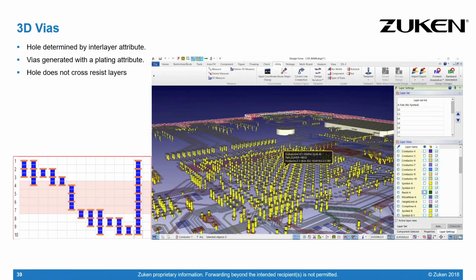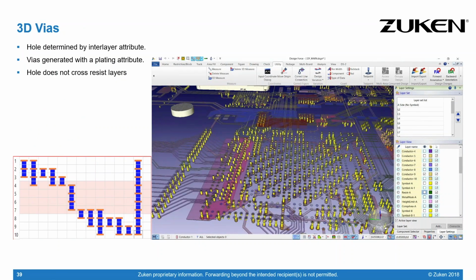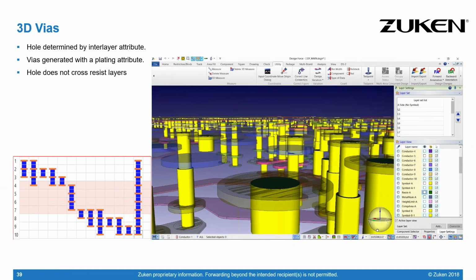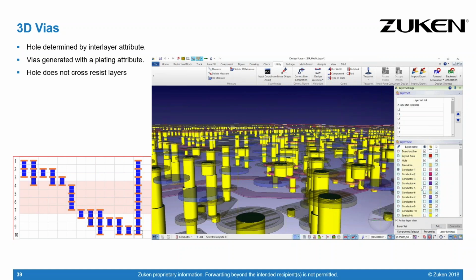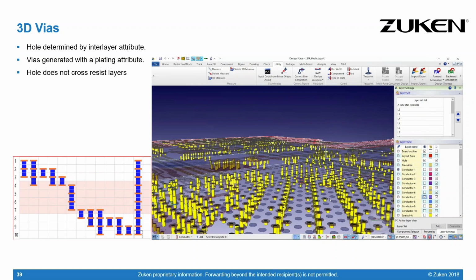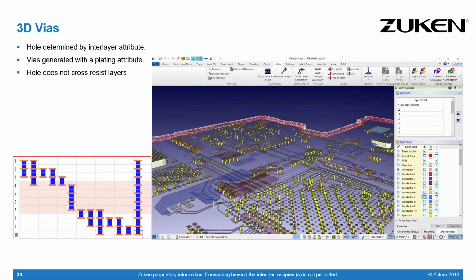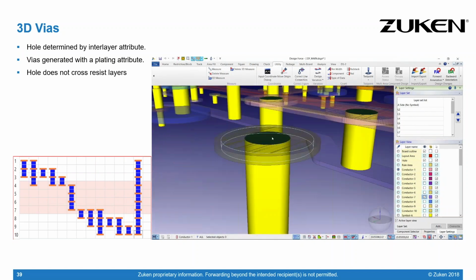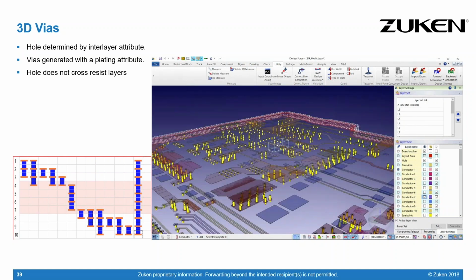One of the key parts for DDR5 is the 3D vias. So why do we have to think about vias when we are doing the DDR5 design? The perceived negative effects of vias may fall into one or several categories. One is that vias are inherently capacitive and change the characteristic impedance of the trace. A via can cause a step function change in the trace impedance, and therefore cause reflections as well. And when a trace moves from one layer to another layer, it becomes referenced to a different reference plane, therefore severely distorting the characteristic impedance of the trace.